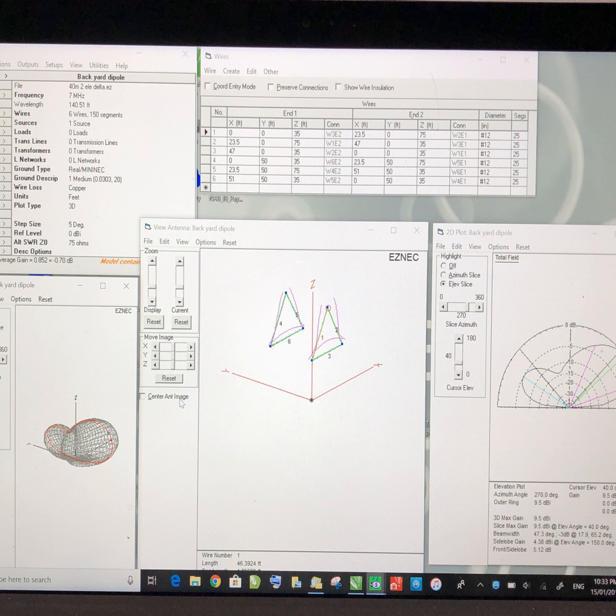But it's also very useful, before you go through that stage, to have a test with an antenna analyzer. I've had one of these now for probably about 7 or 8 years. It's a really useful tool. Essentially, instead of plugging the coax feed back into your radio, initially you put it into the antenna analyzer, and you can control the frequency, and you can control the range of frequencies that it will scan.